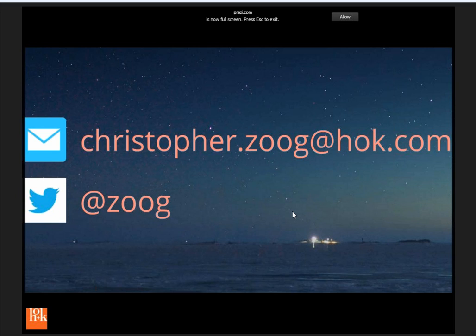Also, I think the important thing about the IFC, and particularly things like the model server, is that it starts to become a platform, like when anybody books flights on Expedia or Kayak.com, right? That's all possible through web services and open standards. Like with airlines, you don't download a whole copy of every airline's flight schedule. The minute you do that, it's out of date. It's all based on a server. So if you imagine this, it's not that far in the future where, if we were working on a design, publishing our designs out to a model server, the authorities having jurisdiction can connect to our server and just basically ping our server and run a code check, or maybe a pre-validation code check on a design that we're about to submit formally in the next month.